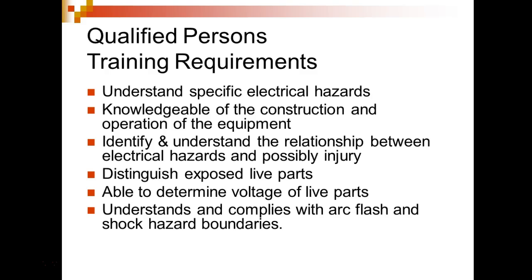Know what voltage. Don't use a meter to see what's there. Use a meter to verify what's supposed to be there. So before you put a meter in a circuit, you're supposed to do what? Know what's there. We had a brand new meter, just brand spanking new. It was a new version by Fluke. And we decided we wanted to measure the voltage on a laser. We had no idea what it was going to be. As soon as we put that meter in there and fired that laser, smoke came up through the meter.